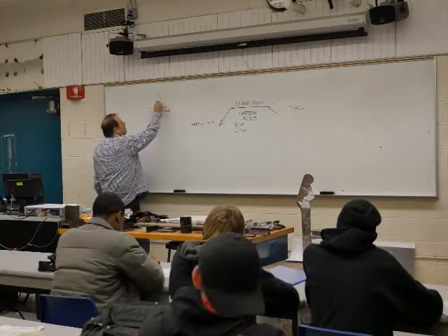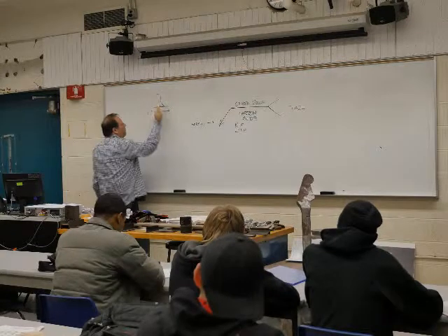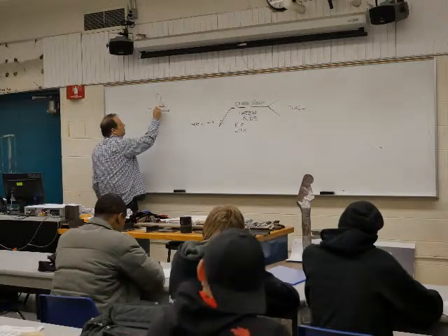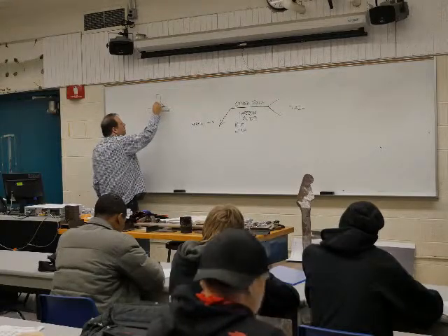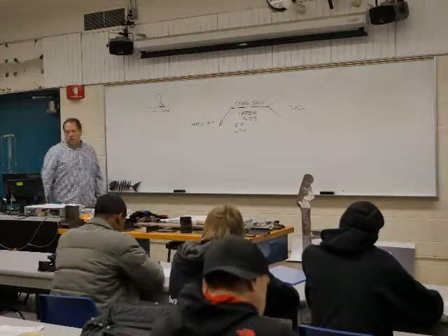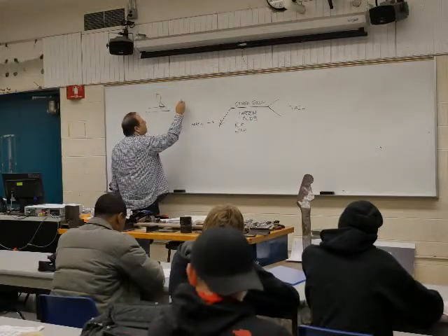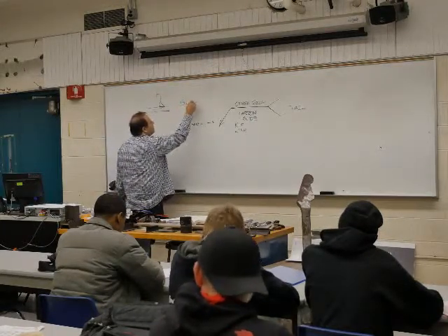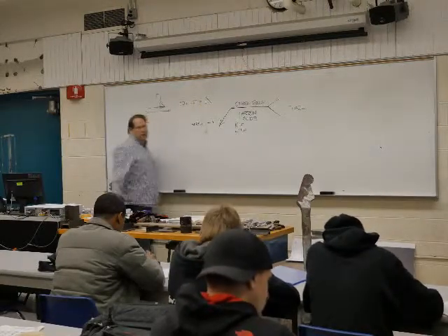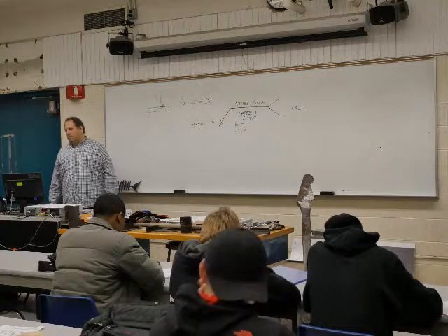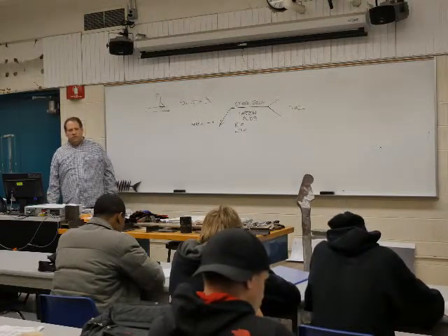So if we just kind of look to the side, this is basically where the weld is going. Now obviously there's going to be some penetration into it, but this area right here would be the weld area, right? So guess what? The fillet weld symbol is that. It's exactly how it looks basically on the drawing like this.